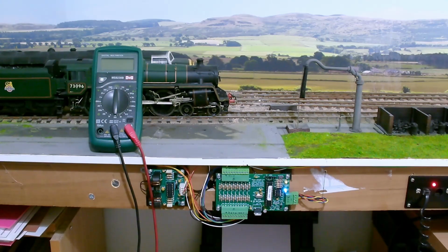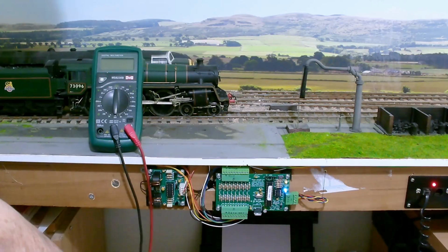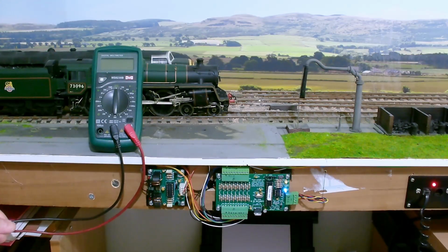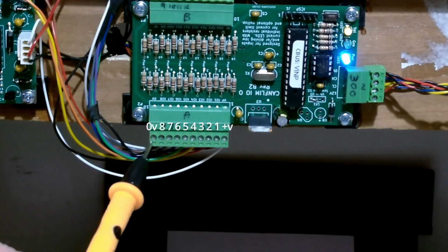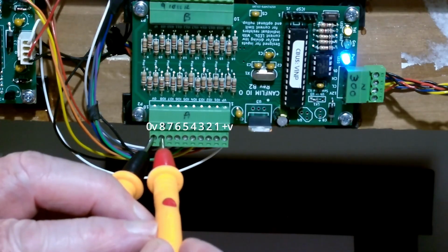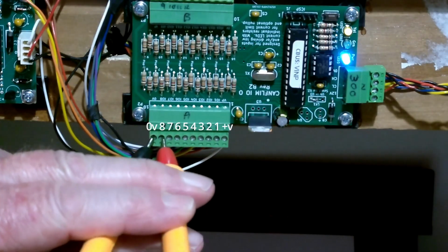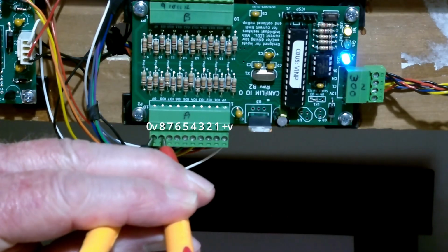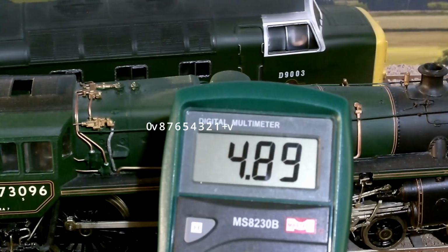The next thing to do is to follow the lead through, and it comes at point 8 on here. So the next thing to do is to check the voltage. 0 volts with a negative probe, the positive probe with a meter at point 8, and it should show us, if it's switched to the 20 volt range or something above 5, it'll show us about 5 volts as it has here.